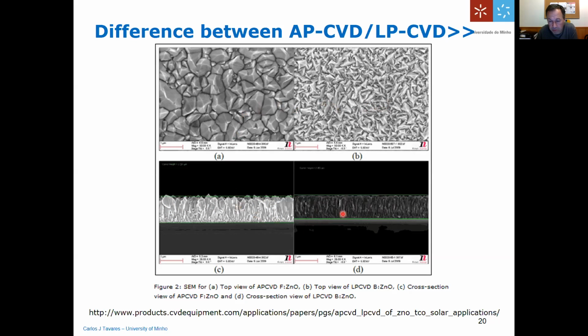Okay, so there are advantages for these types of coatings. Of course, if you need to have a surface which has a lower friction, then you have to have a lower roughness, and then you would have to choose this type of coating. On the other hand, if you want to have a surface which can be abrasive for particular applications, then you will require the film surface with a higher roughness.